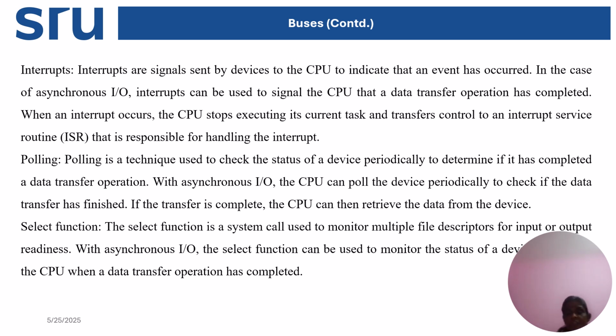If a clock is available, then there is no need to indicate the starting and stopping. But it is asynchronous, that is why. When the transfer is starting, the CPU does not know. When the transfer is ending, the CPU also does not know. So it has to be indicated, informed to the CPU. That is what the interrupt signal is here.